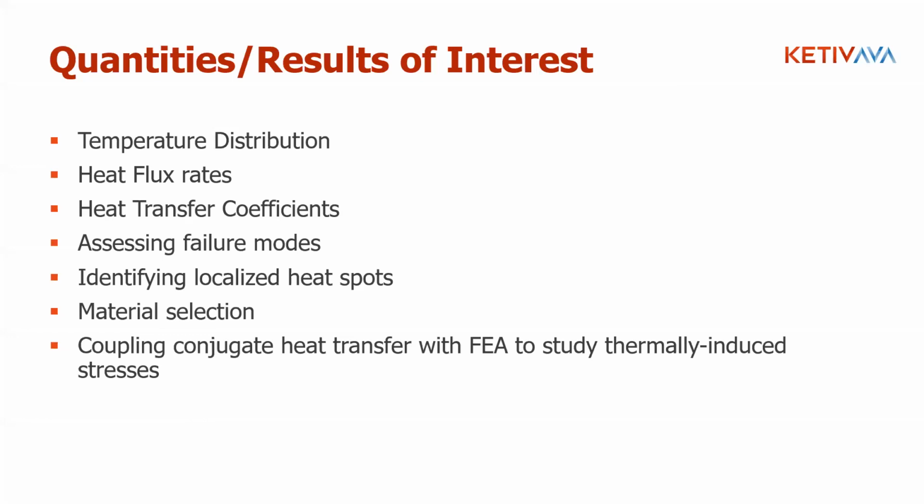The other thing is that you could always use your heat transfer coefficient results from Fluent to couple it with structures analysis on the FEA side to understand what are the effects of this heat transfer on the overall structure. That is something that we will be covering in a future AVA session. So if you want to see this sort of an example wherein we do a coupled analysis between, say, Ansys Mechanical and Ansys Fluent, make sure you enter that in the feedback section at the end of the AVA, and that'll help us prioritize that topic.